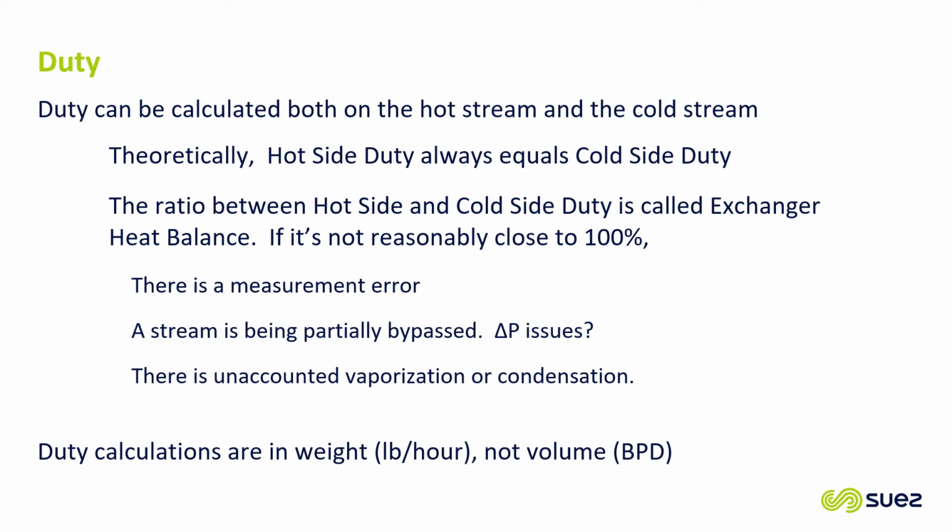Another thing that's really important is that all of our duty calculations that we're going to be talking about in the coming slides are in weight. Typically, and for the purposes of this discussion, in pounds per hour, not in volume or in barrels per day. This is an artifact of the way refineries do their calculations. Heat exchange calculations are always in pounds per hour, so we're always going to be dealing with that.